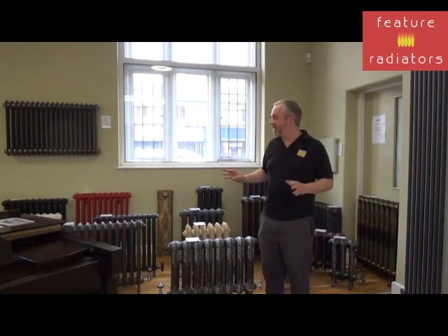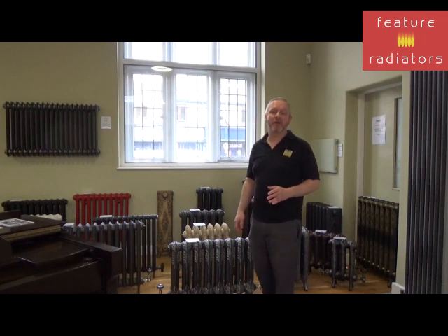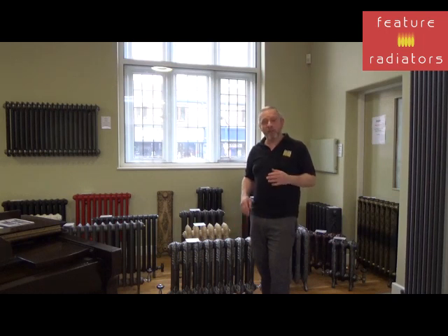Alright, so as you can see, a little bit of change of scenery. With the calculation that we've already done, it doesn't end there, so there are other factors that we need to consider as well. One of those is windows. If you've got double glazing, for example, and you don't have huge amounts of glass, you could normally take about 10% off the calculation we've done, or if it's single glazed, just leave it as it is.